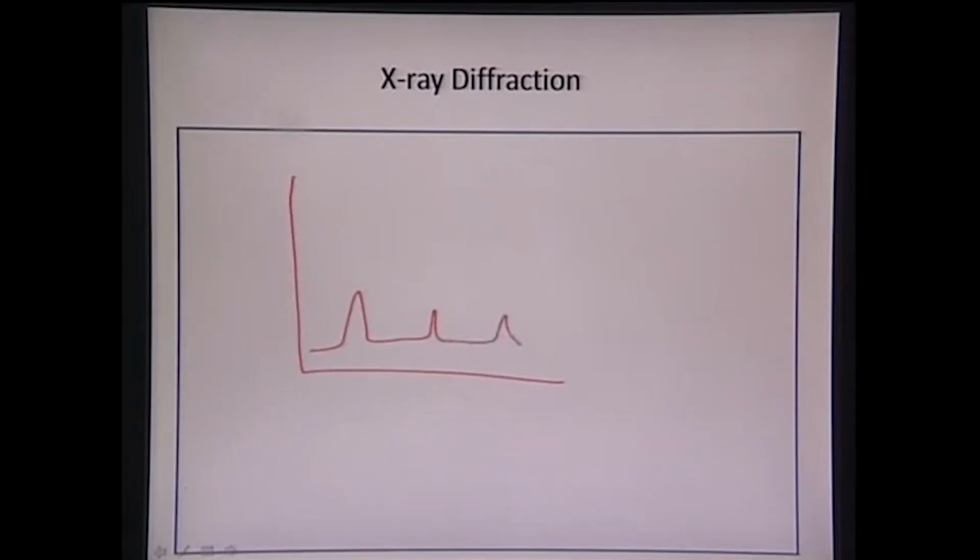It has certain peaks of hydroxyapatite. But since the CNT content is so small and the hydroxyapatite peaks are much stronger, we will see approximately similar coating with a similar kind of peak. This is 2 theta, this is the intensity. We will see peaks at similar locations even for hydroxyapatite with some CNT reinforcement.